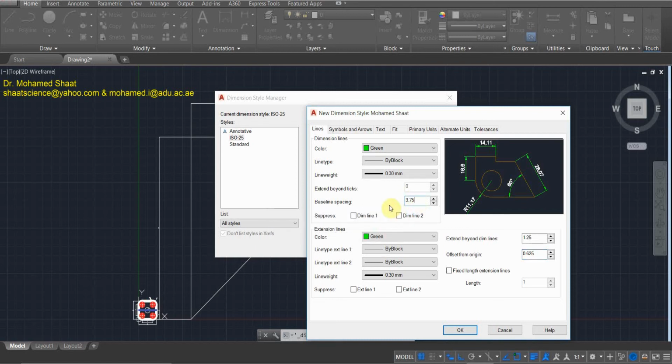So how much do I have to increase this number, and this one, and this one? I don't know. There is no specific standard, but I'm going to give you a guide here. Your objective is just to calculate 5% of the maximum dimension. The maximum dimension in this drawing is 1000. So 5% of 1000 gives 50 millimeters. Just record this value. Save this value. This is your reference.